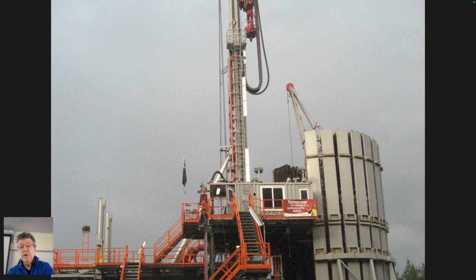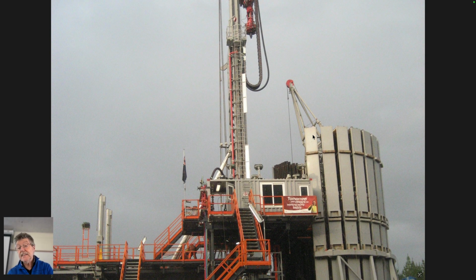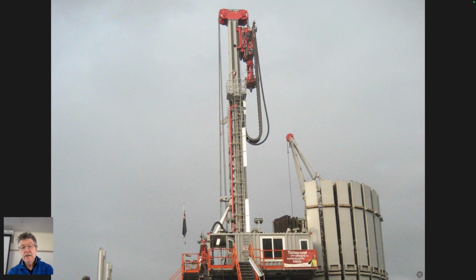The drill rod for this is in some kind of a cassette, basically, where behind these individual components are maybe 5 pieces of 20-foot or so long drill steel, which gets automatically hoisted into the mast, coupled up with a rotating component here, and then added to the bottom of the drill, which is already in the well.